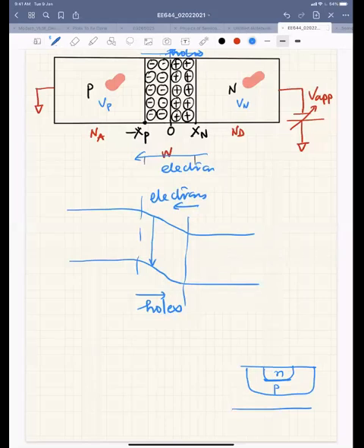But even if you anneal the junction at very high temperature, let's say 1000 to 1100 degrees Celsius, not all of the damages are healed. So in the junction, you always have some defects present. And if your fabrication process is very bad, then you have more defects at the junction. So this junction has defects, and recombination mostly happens at the junction region.